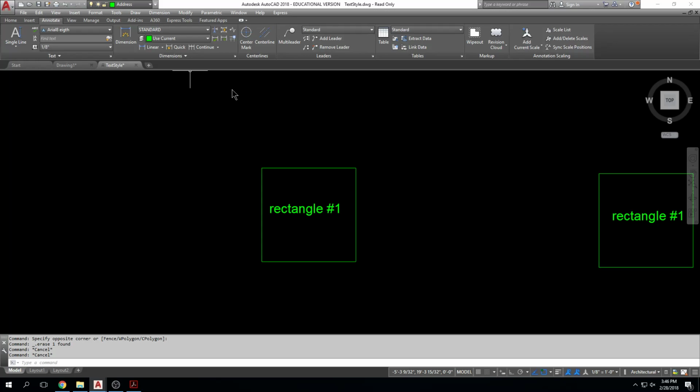and again, kind of due to the fact that when you have to scale objects, you have to make the text on them larger to then scale down to paper space, right? That whole idea of scaling text, that applies to dimensions because you have text on dimensions, right? So dimensions were one of those things where the way that we used to do it is we used to have 15 or 20 different dimension styles so that we had a dimension style for every scale that there is out there, 1/8 inch, 1/4 inch, 1/2 inch, 1 to 1, 1.5 inches, 3 inches, 6 inches to 1, right?